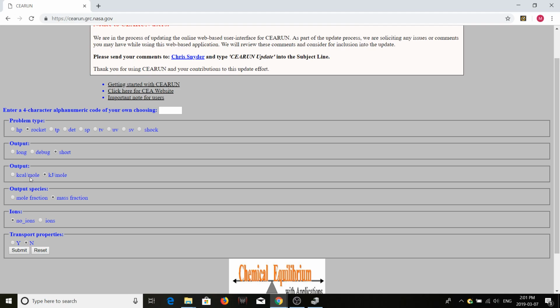Anyway, output species, species being gas species and fuel species. This is regarding the fractions of the different chemicals involved. Do we want the mole fractions of each gas, fuel and propellant, or the mass fractions? We want mass fractions because we just end up converting mole fractions to mass fractions anyway. There are some cases where you'd want the mole fraction, but it gives you the molar masses, so you can just calculate those yourself. Mass fractions are more immediately useful.